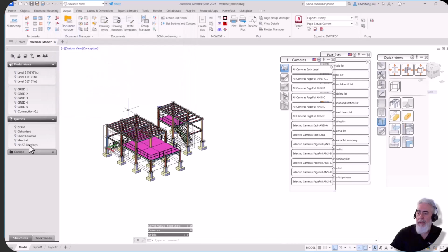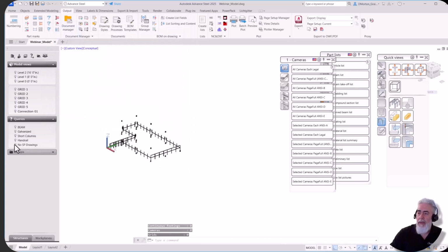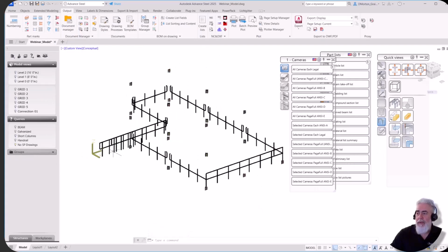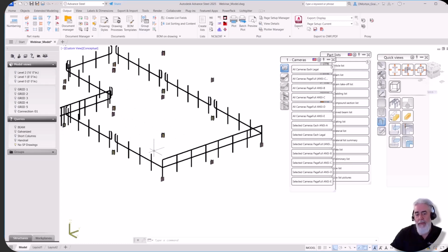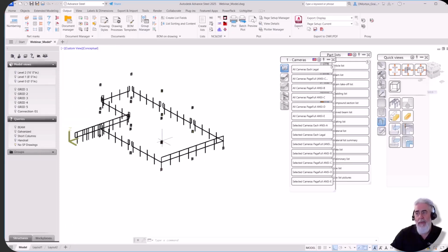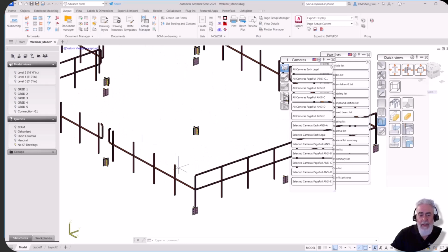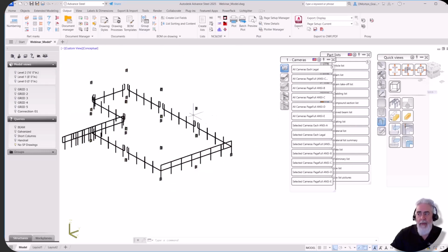And if I look at this no SP drawing, if I check the bulb, it shows me these parts do not have a single part drawing. You'll notice the other structure completely disappeared, because I've got the drawings for that one. On this one, they're either main parts or they have common parts between the two structures. What's different is the ones that are showing up here. These ones are the ones that do not have single part drawings. In the case where the top handrail is missing, that's because it's the main part, right? So it's looking only at the single parts of each assembly.